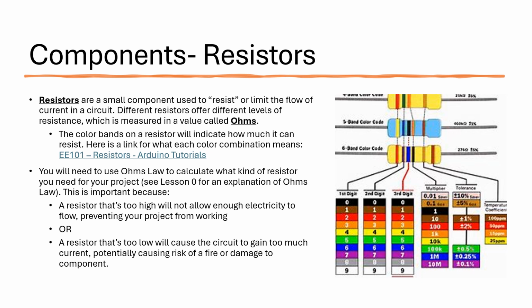When looking at our resistors, the closest value would be the 220 ohm resistor, so that's the component we'll use for this project. To save time in future projects, you'll be told which resistor to use, but make sure to know Ohm's law for future reference.